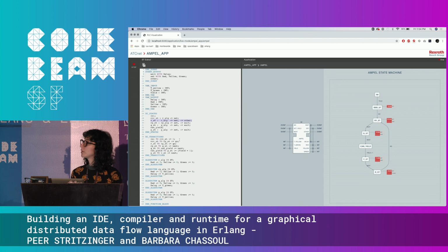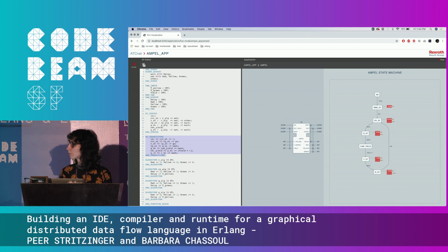Is there something else that you want to explain on this? Yeah, basically these transitions are triggered by events, and that one is not triggered by an event. There's no event: whenever it gets into this state and this condition is true, it does the next transition immediately. But you can have both: if it's in brackets, it's a condition, but you can have an event and a condition. You can say, if this event triggers and this condition is true, then do this transition. So it's a pretty complete state machine implementation.